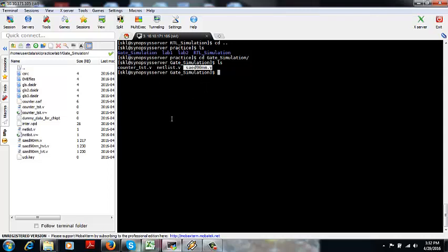which has been provided by the vendor, which will have the information about the cells that have been generated in the netlist. Okay, so the cell information has to be given, right? Because the netlist.v file will have various cell instance names only. The VCS compiler won't understand them. So the detailed information about the various cells is available in SAED 90nm.v. So the target technology library is important in this case.